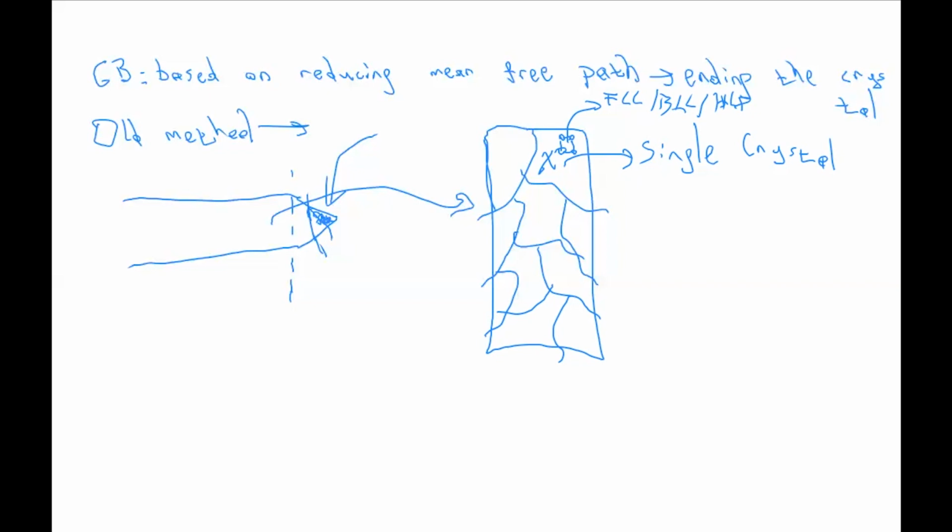With the repetition of the unit cell, we have systematic packing of atoms. Therefore, each grain has a different orientation. This unit cell will repeat itself with the same crystal structure, but the orientation of the unit cell is this way, and this is this way. So atoms are oriented in different ways in 3D.